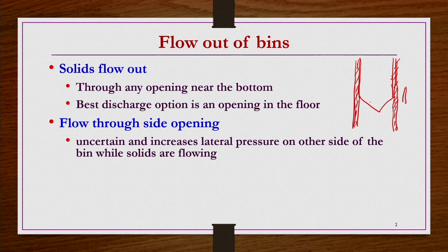So, when you are filling the solids, a kind of vertical stress distribution is possible in these sections, and then a slightly vertically inclined kind of pressure distribution is possible inside the bins, right. But when you are opening from the sides like this, what happens is a kind of lateral contraction of the solids may take place, and then the distributions may be something like this, something like this. So, that distribution may not be helpful, especially with respect to the walls of the container.